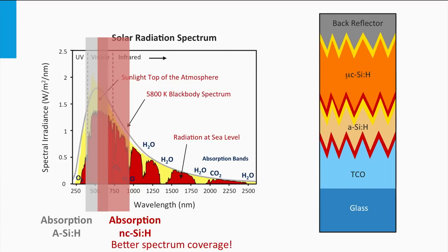First, the amorphous junction has the highest band gap of both materials and will act as top cell. The top cell is the PIN junction that is facing the front and where the incident light is passing first. The cell with the highest band gap acts as the top cell, as the spectral part with the most energetic photons has the smallest penetration depth in materials. The bottom cell is the cell with the lowest band gap. This cell has to harvest the photons from spectral parts with the lower energetic photons.